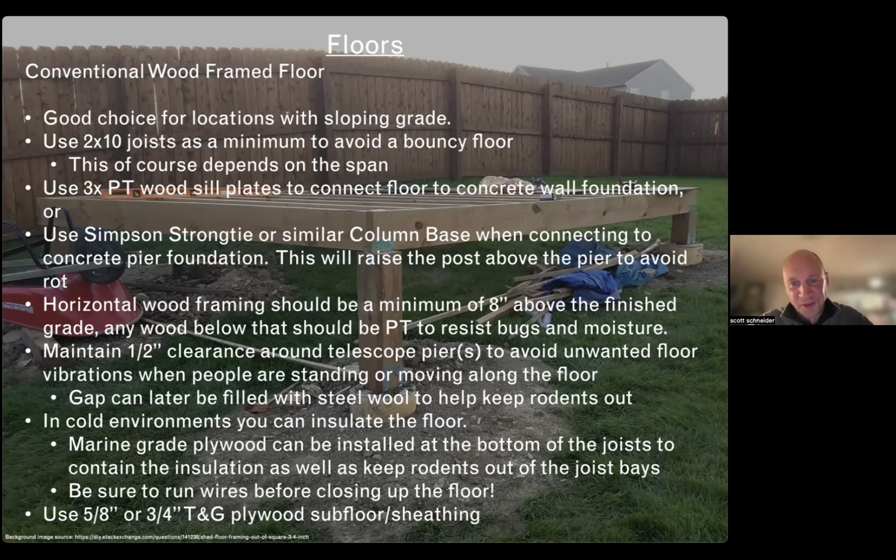This is another thing that depends on the ground, the soil, and it has to do with deflection. Even if you're not getting a permit, the building code specifies the maximum deflection value, and it's driven by the soil and what it can withstand.